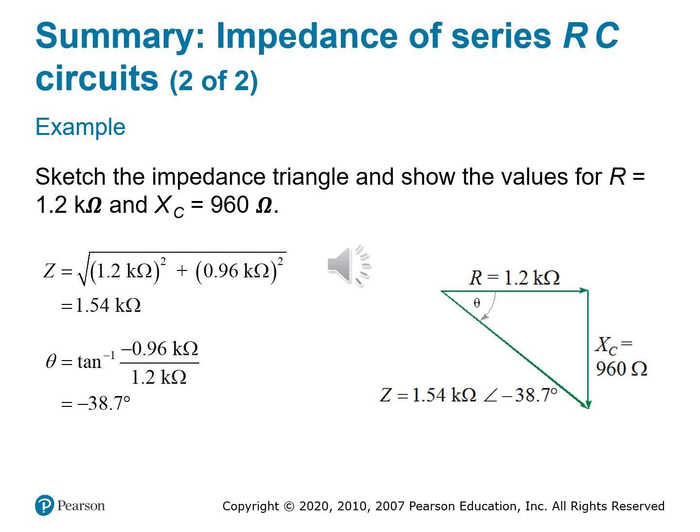And this matters because when you're designing or troubleshooting RC circuits, this triangle tells you how much opposition or impedance the source sees. It reveals how out of phase current and voltage will be. So it lets you predict behavior without hooking up a scope, and it just lets you know what's going to happen. It's exactly how we approach inductors, but remember that with inductors, the reactance triangle went up and the current lagged, but for capacitors, it's downward and the current leads.